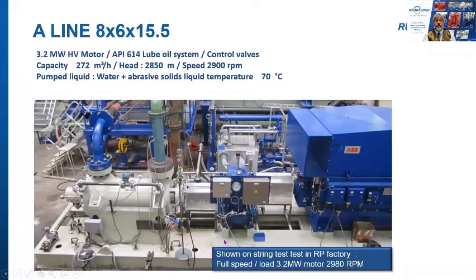Now here is a big BB5 pump undergoing a string test at the Witten factory. It's fairly common to have tests on these big, expensive, complex packages, and the Witten factory is set up for this. I consulted a friend of mine, Mike Sorrell, who is with Sulzer Pumps, and he confirmed that their Leeds, UK factory carries out such complete unit tests on their big engineered packages as routine. They can even test with gas turbine drivers, such as a Rolls-Royce RB211 or a Solar Titan.